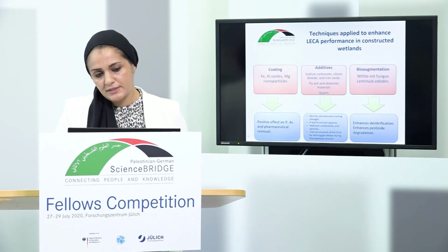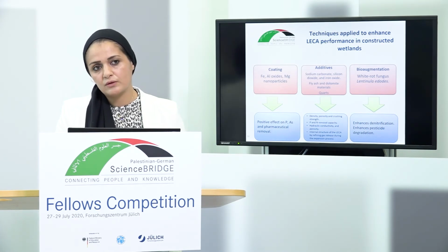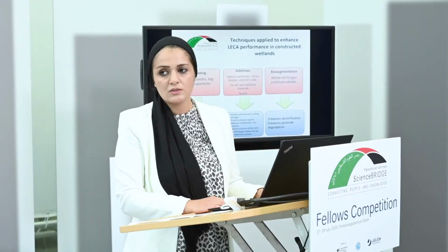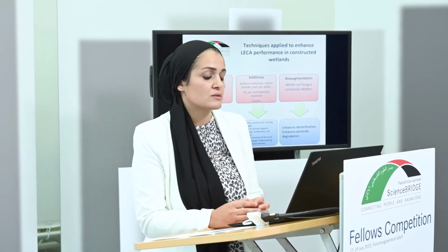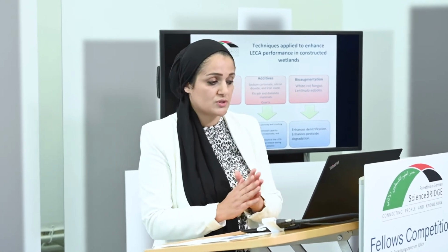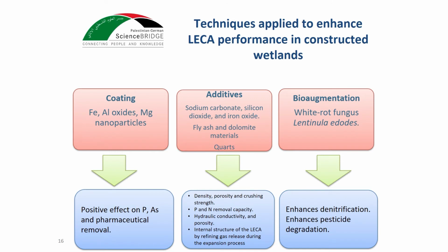In recent years, they have introduced many techniques to enhance the performance of LECA. They use coating, so they coat this material with iron and aluminum oxides and magnesium nanoparticles. This coating has a positive effect on phosphorus and arsenic absorption and removal.